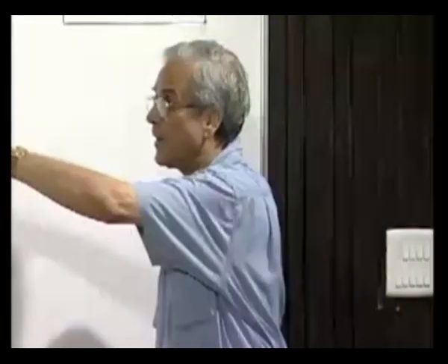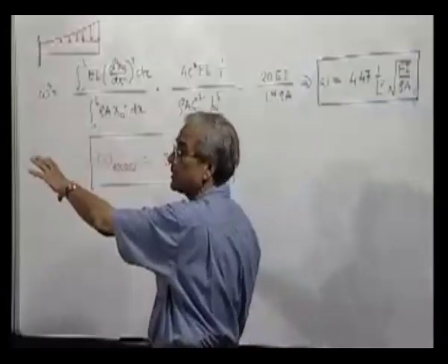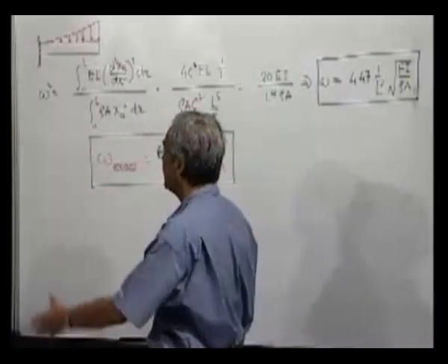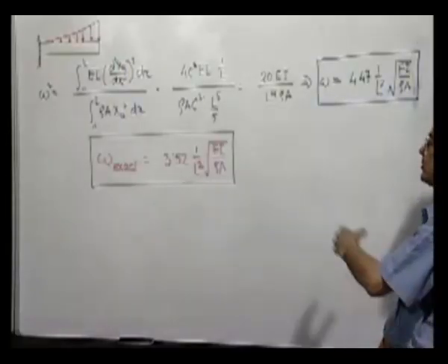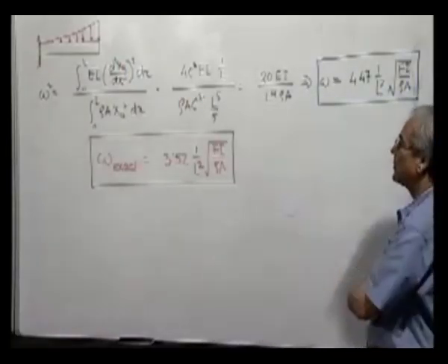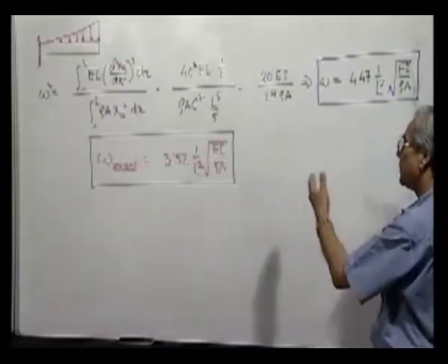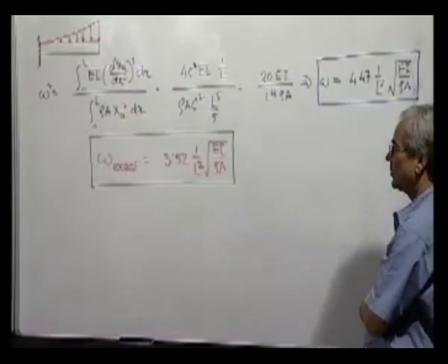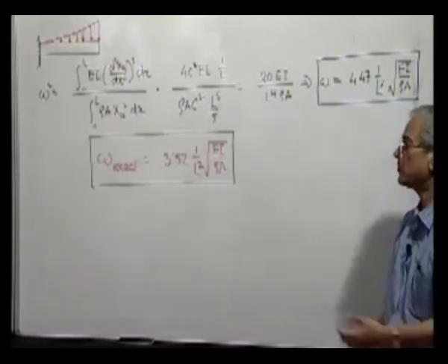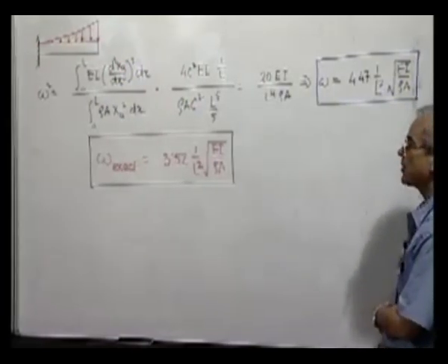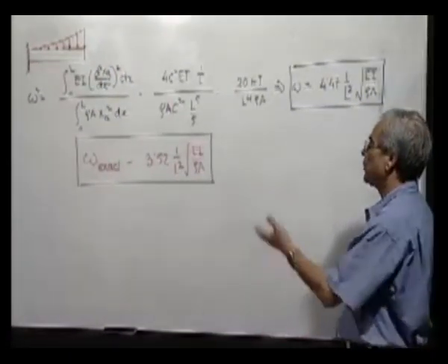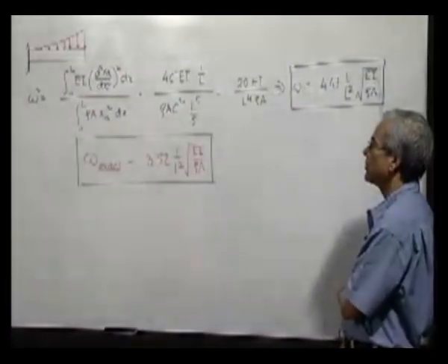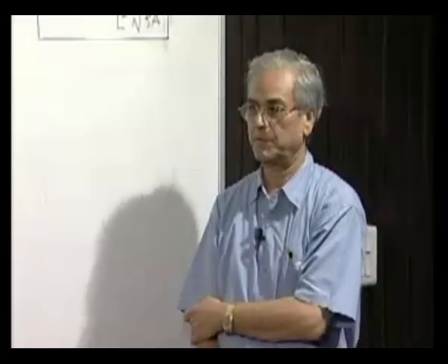If we can find out the second mode shape and put it there, obviously we will get the second mode, but most of the time it is convenient to solve the problem satisfying the boundary conditions, which will give us the first mode frequency. So in the next presentation, we will try to see if it is possible to get a methodology by which we can have some approximate values of the higher frequency.